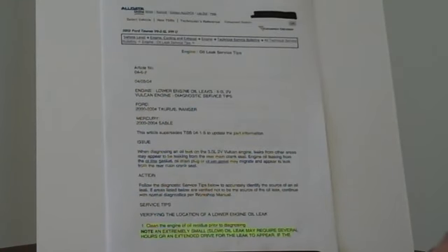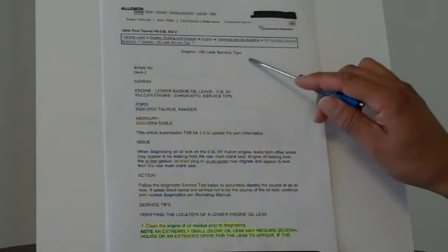A technical service bulletin entitled Engine Oil Leak Service Tip states, clean the engine of oil residue prior to diagnosing. Note, an extremely small or slow oil leak may require several hours or an extended drive for the leak to appear. Now, if the engine is not clean, prior oil residue may lead to a false diagnosis. These statements would also apply when checking leaks in other systems, such as the cooling and the power steering system. This is not only basic knowledge, but also plain common sense.